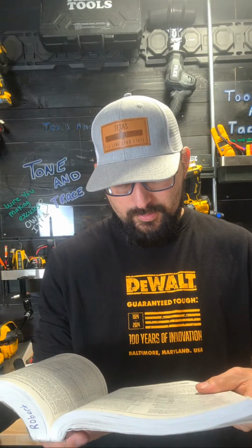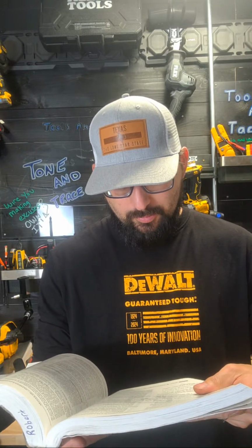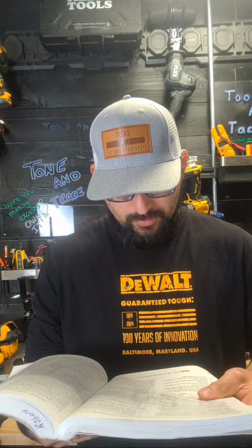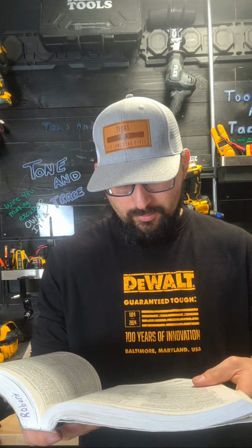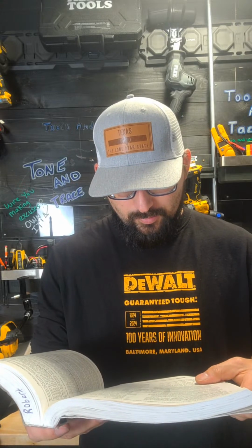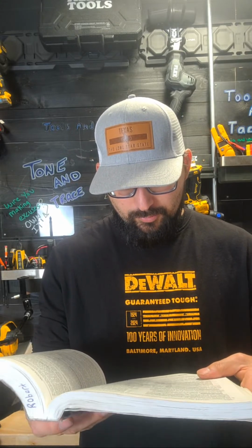Flammable liquid produced vapors or combustible liquid produced vapors can exist under normal operation conditions, in which ignitable concentrations of such flammable gases, produced vapors, or combustible liquids above the flash points may exist frequently because of repair or maintenance operations or because of leakage. 3, in which breakdown or faulty operation of equipment.